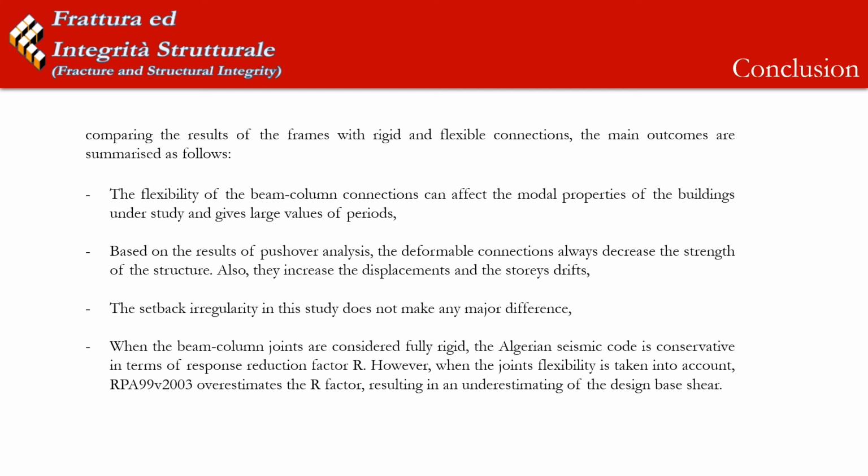and gives larger values of periods. Based on the results of pushover analysis, the deformable connections always decrease the strength of the structure. Also, they increase the displacements and the story drifts. The setback irregularity in this study does not make any major difference.